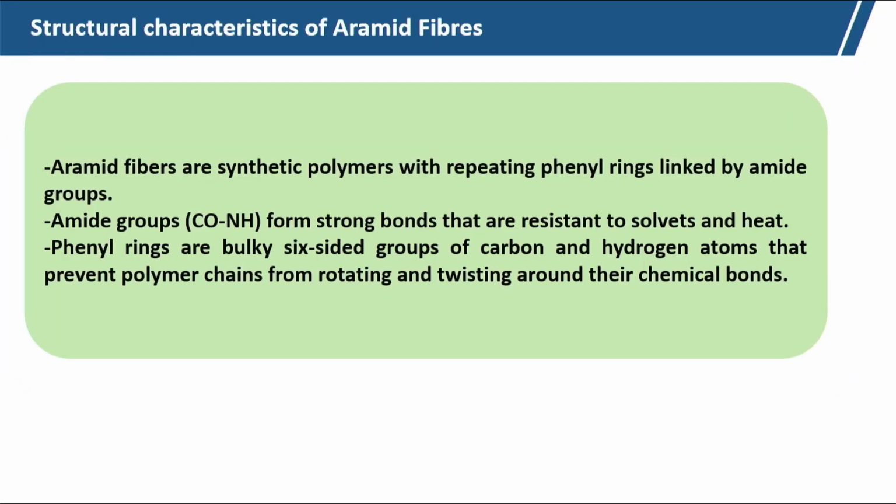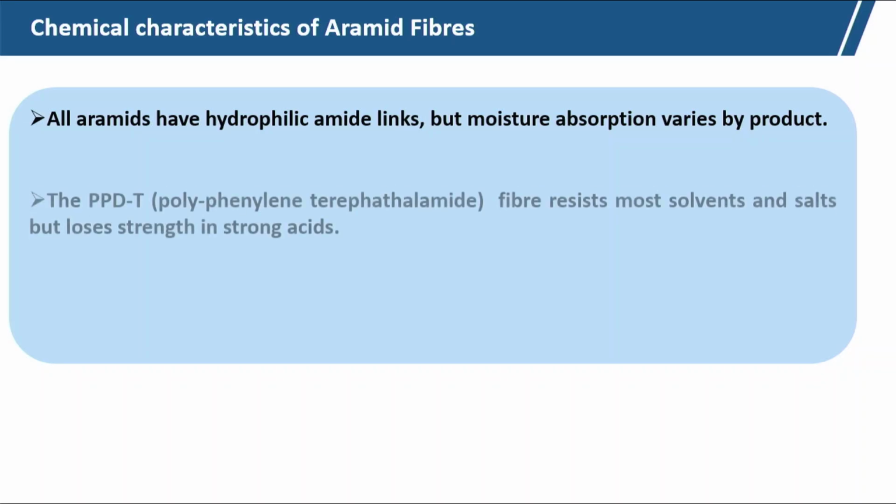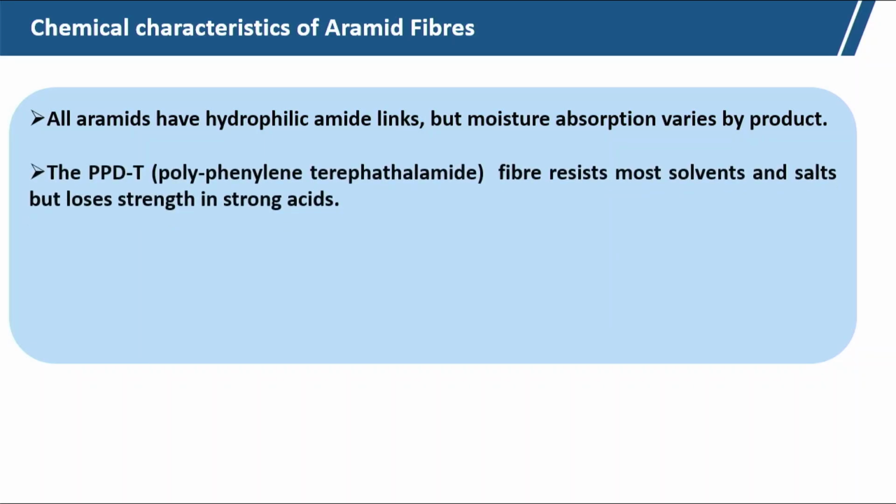Now, these are the structural characteristics. Now, let us come to the chemical characteristics of aramid fiber. All aramid fibers have hydrophilic amide links, but moisture absorption varies by product. The PPDT fibers resist most salts, but lose strength in strong acid. These are the chemical characteristics.